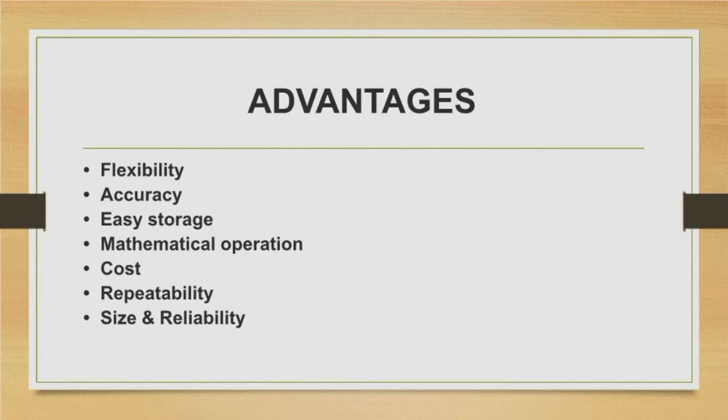Now I will give the advantages of DSP processor. These advantages are compared to ASP only, analog signal processing. First one is flexibility. Why do I say DSP processor is more flexible when compared to ASP? Because if you want to modify or reconfigure your system, you can simply change the software program, it's enough. So DSP processor is more flexible. Next thing is accuracy. DSP processors have more accuracy when compared to ASP, because analog signal processors can face component tolerance problems and breakdown problems, etc.